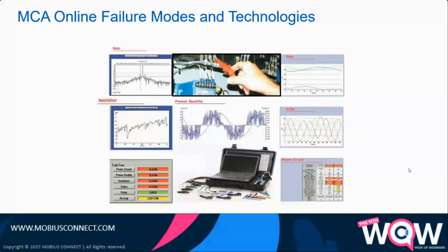Next slide. And also to mention, motor circuit analysis offline means that the motor is not energized. You're typically connecting the MCA test equipment right to the leads within the motor junction box, or what's referred to as the pecker head, right? And then you go to motor circuit analysis online. Online is when the circuit is fully energized. You're collecting your data from your MCC connections there, and you're actually looking at the entire circuit all the way through the motor and even beyond. Next slide, please.